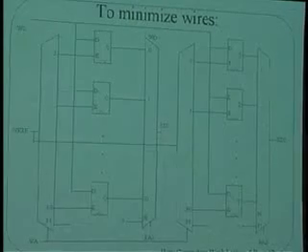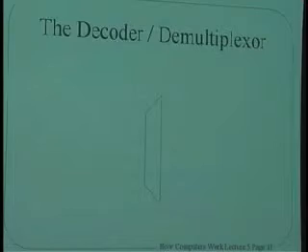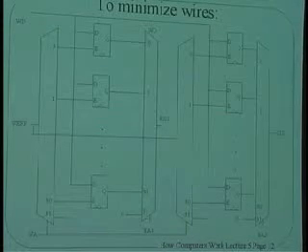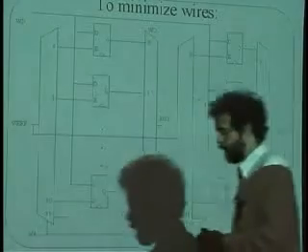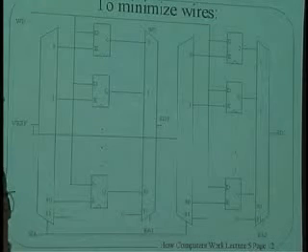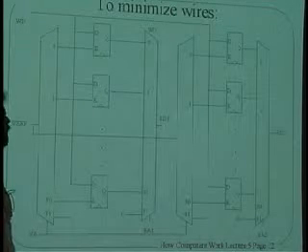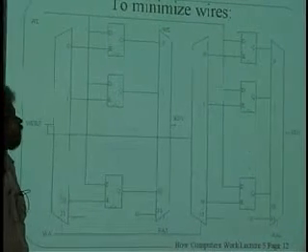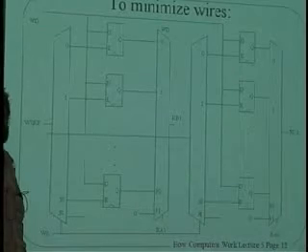Okay. So we need to understand how this thing works, this decoder. It's also called a demultiplexer, the same way the other one is called a multiplexer. And I basically told you how it worked, how it took an input and chose the different outputs. Turns out you could implement this a slightly different way. And there were computers like, I know the PDP-11 did this, I think the VAX did this too. This was a standard trick, I think DEC even had a patent on this, for how to lower the number of wires that crisscross across the register file.